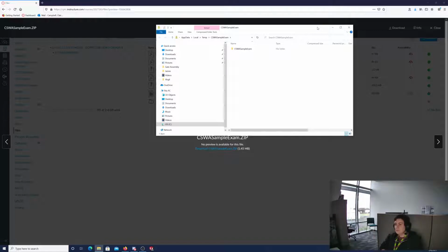So that's something to definitely be mindful of. A lot of the time, it'll print little support structures, and you'll be able to cut those out afterwards with an X-Acto knife or something. But definitely something to be aware of.